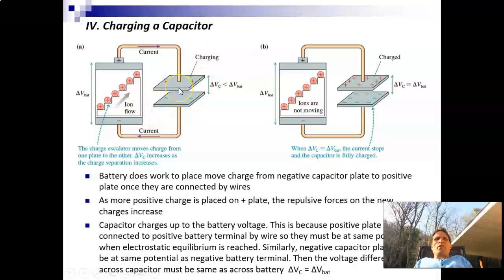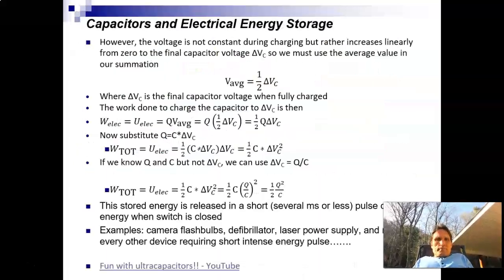So you may think it's funny, but it's not. People accidentally short capacitors all the time when they're going in circuits, and if you accidentally touch these two electrodes at the same time with a screwdriver while you're reaching in there, you can short this out and you can kill yourself. So don't do it, or if you do it, know what you're doing.